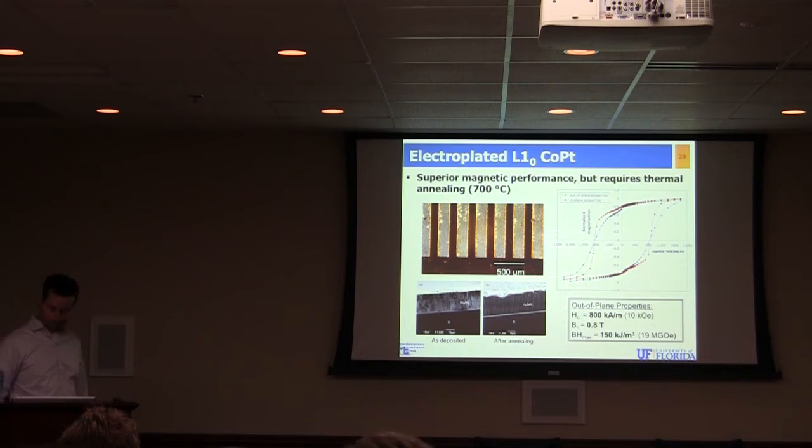So what's the impact of the annealing on the top surface? Because I see all those roughnesses at the top. What order are we talking about? Yeah, so the surface roughness here, you do see the surface does get rougher, and that is associated with this phase change. There's also some cobalt segregation. So you actually get a cobalt platinum pillar surrounded by a cobalt-rich grain boundary, which actually helps enhance the magnetic properties. Because I think that's why we see this type of polymer structure. What is the Curie temperature of this material? This one is about 560 Celsius.